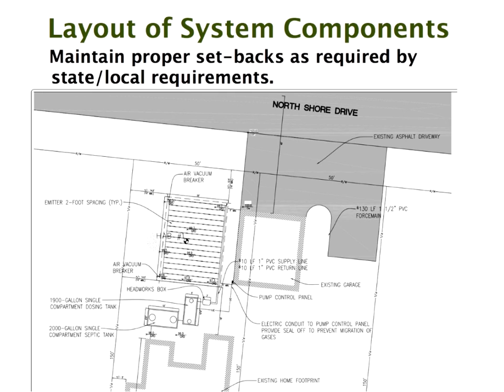to a drip system, just so we can afford a little bit more settling, and the provisions for effluent filters and pump discharge filters prior to the headworks box to filter out as much suspended solids as we can. And like I said, our experience has been pretty good. I don't know of any failures related to the drip systems. We've had some complaints regarding the advanced treatment systems connected to them, but I'm unaware of any that have failed due to the drip